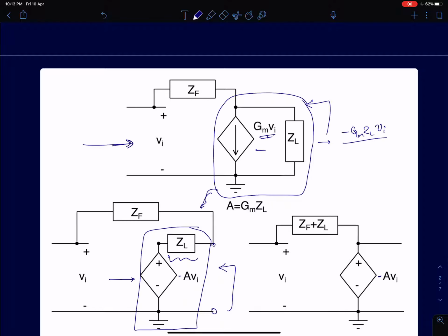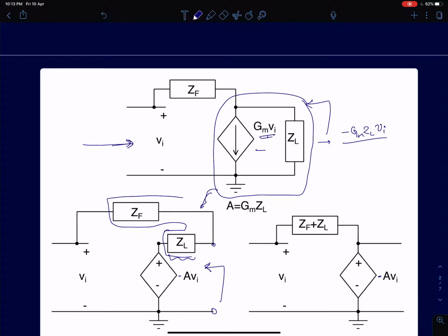series. Now, if you recall from the previous lecture, we have reduced this to a problem where the dependent voltage source has a finite output resistance. So all I can do is club this resistance along with the impedance ZF. Then you get this circuit. Once you have this, this is your familiar Miller's theorem circuit, wherein Miller's theorem is applicable. The output voltage has to be a dependent source for you to apply Miller's theorem.